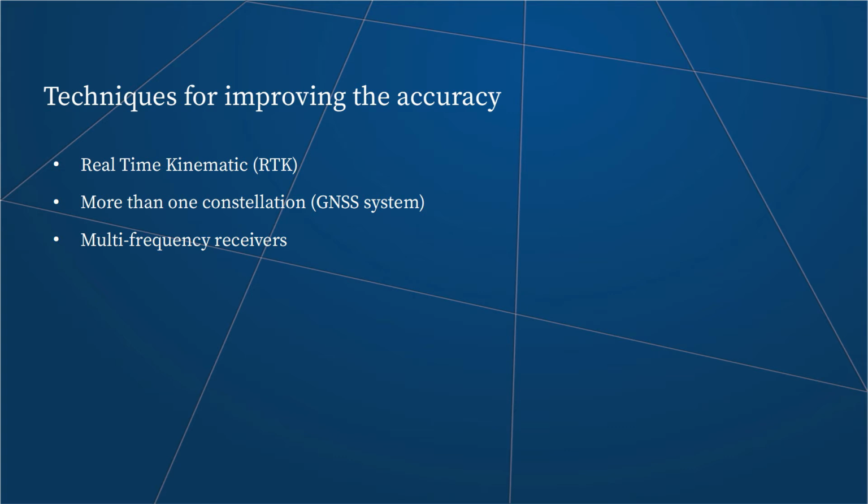When the receiver tracks both frequencies, it is capable of calculating these delays very accurately, and it can almost completely eliminate or compensate for them. The other good thing is that the second frequency is usually much more powerful than the first one, and with a longer pseudo-random sequence.